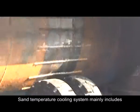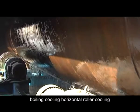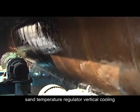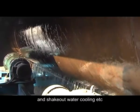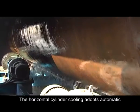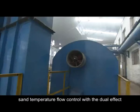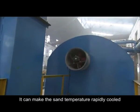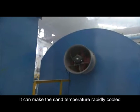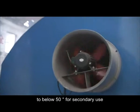Sand temperature cooling system mainly includes boiling cooling, horizontal roller cooling, sand temperature regulator, vertical cooling and shakeout water cooling, etc. The horizontal cylinder cooling adopts automatic sand temperature flow control, with the dual effect of water cooling and air cooling. It can make the sand temperature rapidly cool to below 50 Celsius degrees for secondary use.